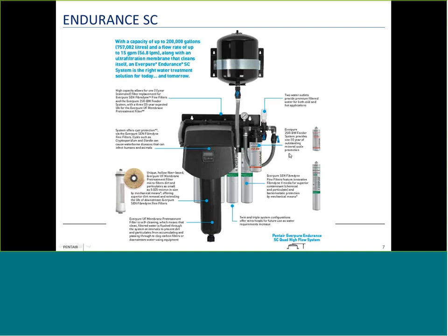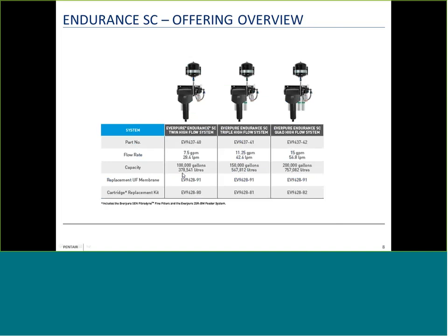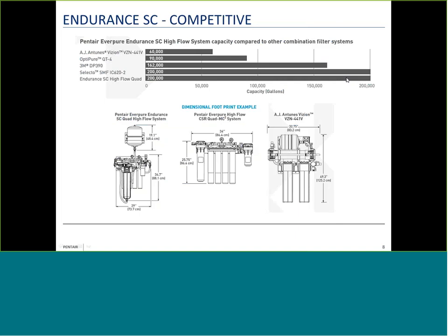Disinfection will kill bacteria and viruses, but it will not leave a residual behind to ensure that. Chlorine is a sanitizer because we're able to create a reserve in the water, or a residual, that is there to work in case of reinfection, whereas a disinfection technology just kills whatever gets through.